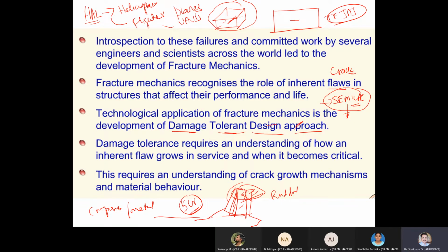Is that feasible practically? After spending 5 crore, the component has this kind of problem. No, it's not possible. Then this term comes: damage tolerant design approach. A set of engineers in HAL have every geometry with them, because we manufacture the component, so we will have the complete finite element analysis and so on. They will reproduce the same analysis again with the crack.